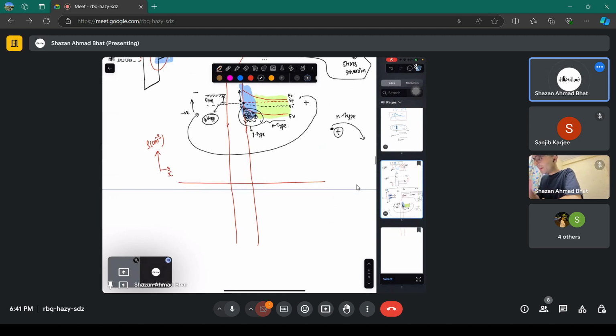When you do it, you show this as something like a step, the positive charge, which are the positive ionized, I should say, the donor atoms. Okay, it's similar to what happens in a p-n junction. You draw the space charge here as this, except on the metallic side you don't have these negative immobile ions because metal is full of free electrons.